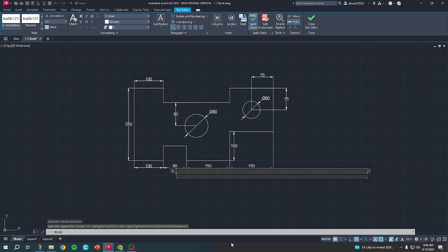We're also going to just take a minute and get into this annotation standard, text height. This is the same situation. You can match the text height that you used, or make it a little bit bigger, maybe 16, to put your name on this and your period on this. Sorry, I just typed that in up here.